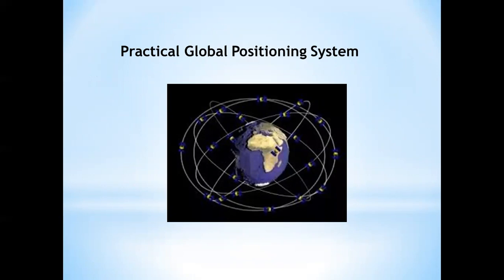The orbits and the locations of satellites in each orbit are designed in such a way that at any instance of time, four satellites are visible from any point of the Earth. This will satisfy the necessity of four spheres required for the exact positioning. The GPS receiver has a clock which tells the current time. It then sends a signal to the four satellites to measure how long it takes for the signal to return. Based on this time, it calculates your position on the earth. A GPS receiver can also show you the position on the map.